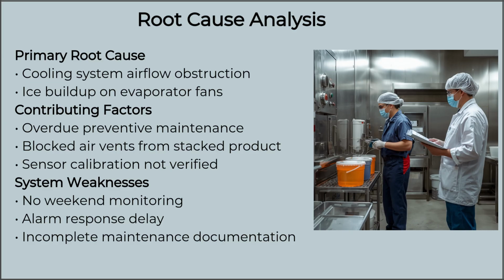The investigation confirmed restricted airflow due to ice buildup on evaporator fans. Frost accumulation reduced cooling efficiency, causing the temperature to rise above the critical limit. The cooling system could not recover without manual intervention.